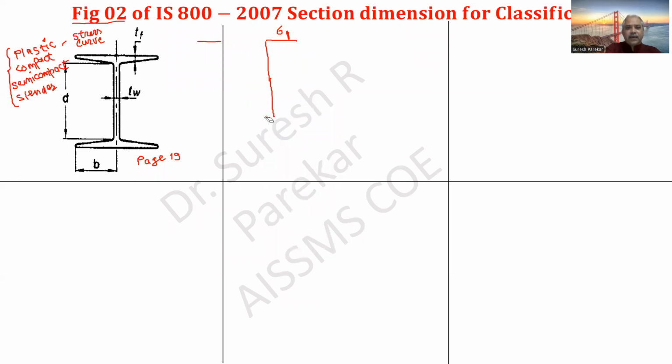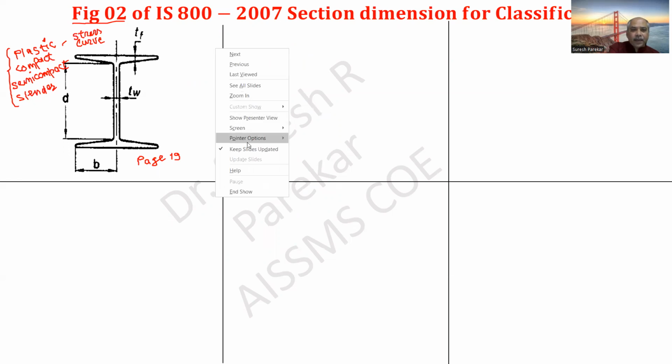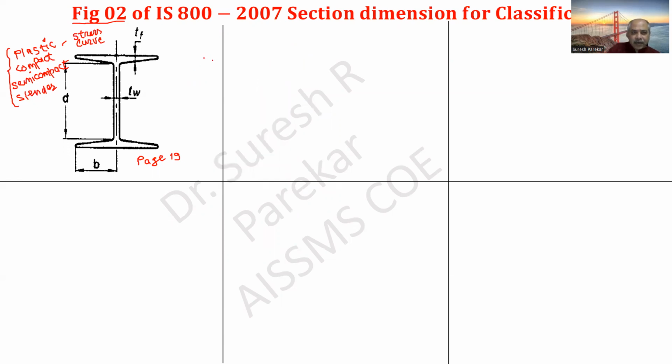All the fibers of this section are at sigma y value. These form a couple which gives us the moment of resistance. So this section is my plastic section.